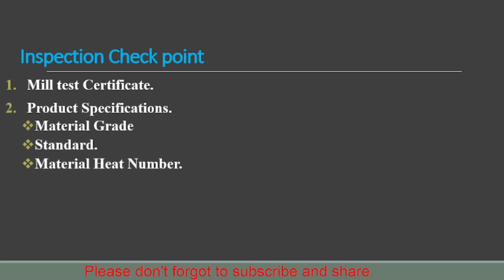Then we have to check the product specification. During material inspection, we have to physically check the product specification on site. In the product specification, we can find the material grade, standard, material heat number, and others. During inspection, we have to confirm that the material has the material grade, the standard it follows, and the material heat number written by stamping or printing.